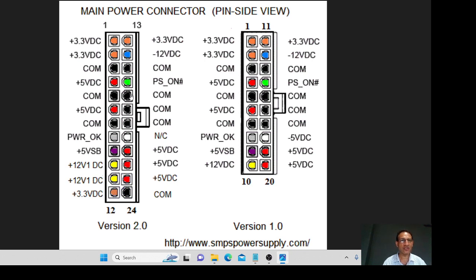That's the way we test whether the ATX power supply is working or not. If the power supply has issues, when you connect these two, the power supply won't respond or switch on. That is why it's very important. An ATX motherboard power supply can be tested like this, but AT never does such testing.